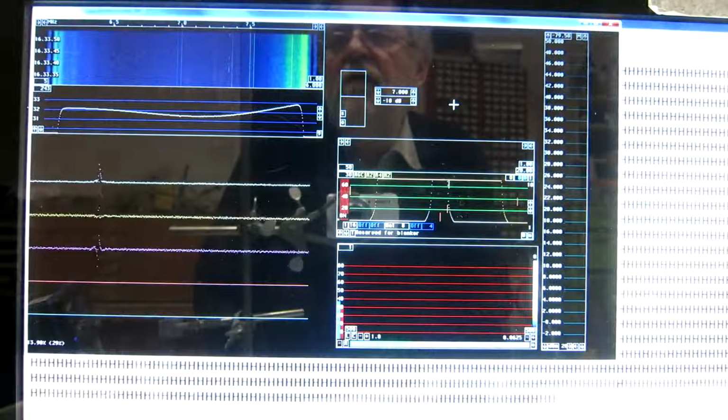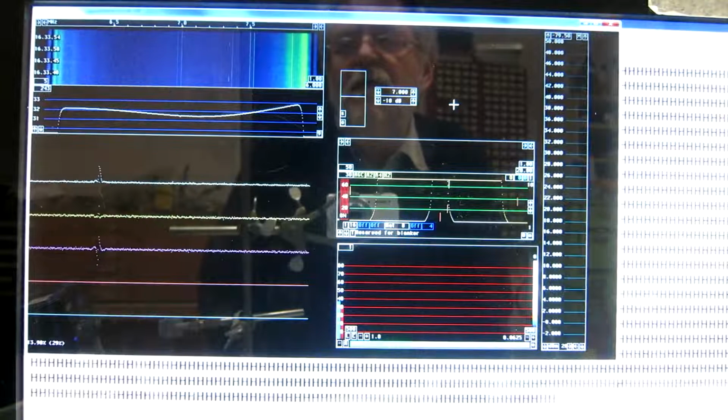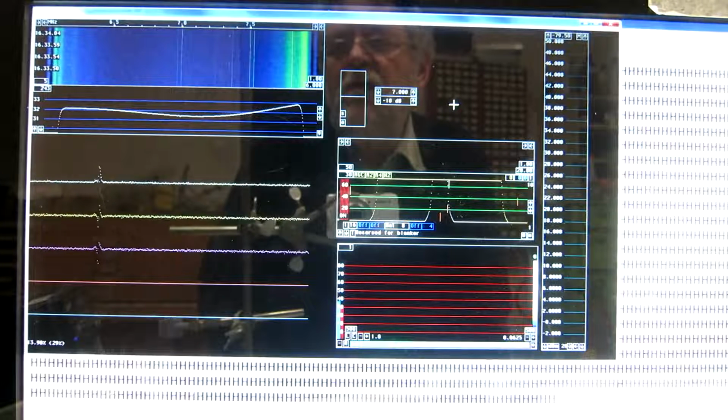The proper generator is close to 50 ohms. I have an attenuator between it and the SDR-IP to guarantee that. And therefore I have to recalibrate with the function generator to get it properly calibrated for a 50 ohm system.